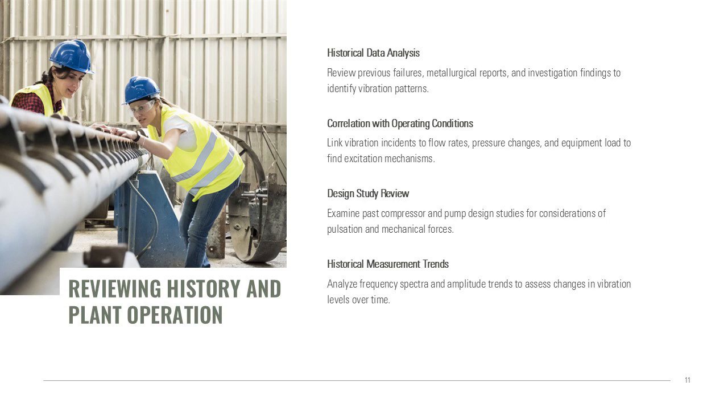This step is essential for distinguishing between chronic design-related problems and issues triggered by recent operational changes. By understanding when and under what conditions vibration occurs, engineers can develop hypotheses about potential sources, such as flow-induced turbulence, acoustic resonance, or structural flexibility. This knowledge forms the foundation for targeted inspections and corrective strategies.